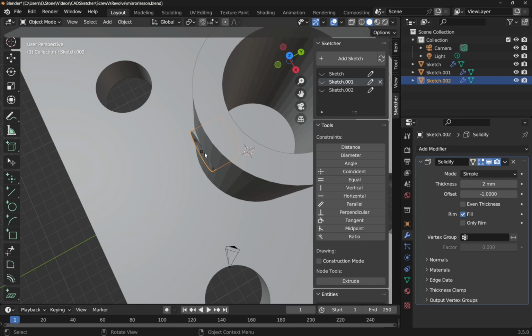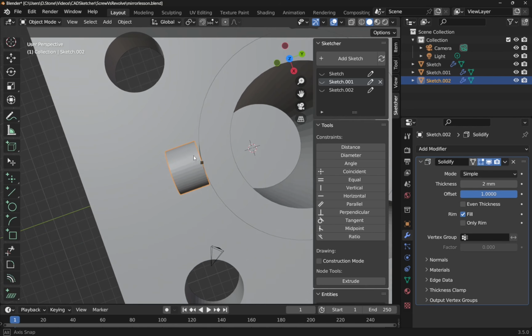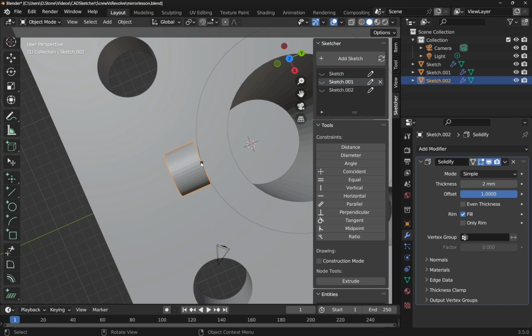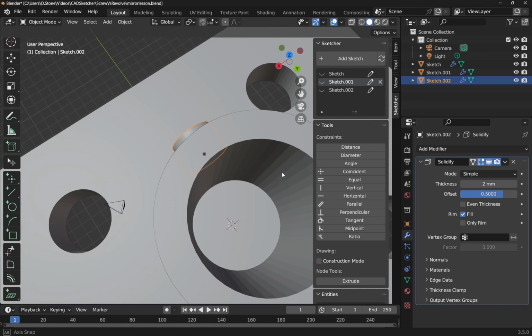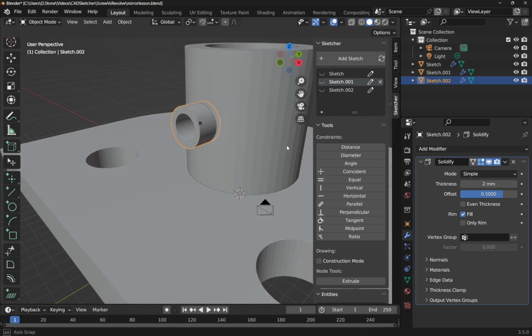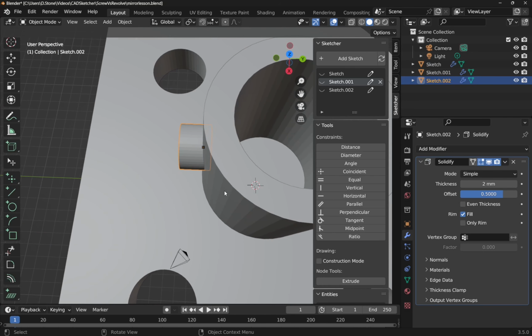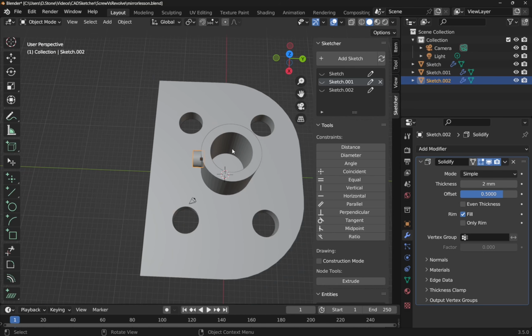And you see that's gone inwards. So that's changed this to 1. That's there. But you can see the gap in behind there because it's gone from the plane outwards. So I'm going to bring the offset back in by 0.5. So we've got that embedded inside there. Now we've got that, let's add some mirroring.